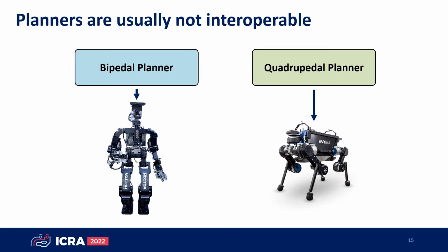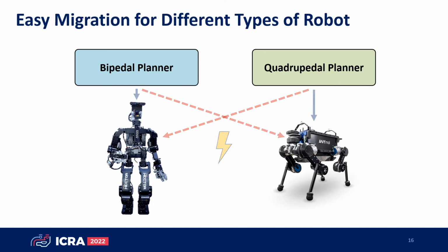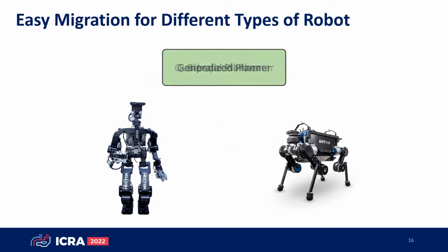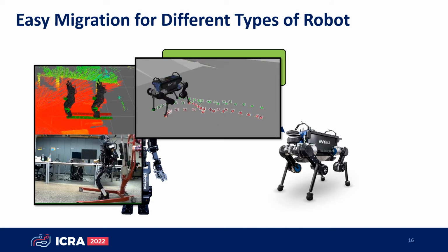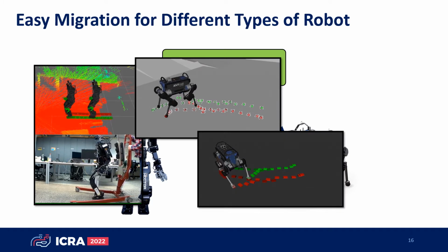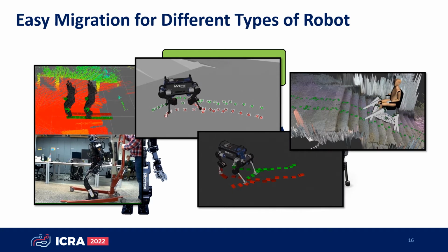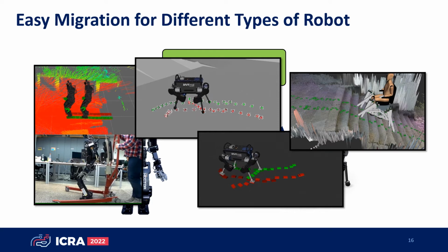Currently, footstep planning systems are usually tied to their target systems and are not interoperable. Our contribution consists of a novel generalized formulation for search-based footstep planning that makes no specific assumptions about the robot kinematics, such as the number of legs, or the used locomotion control schemes, and thus can be applied to a variety of different types of walking robots.